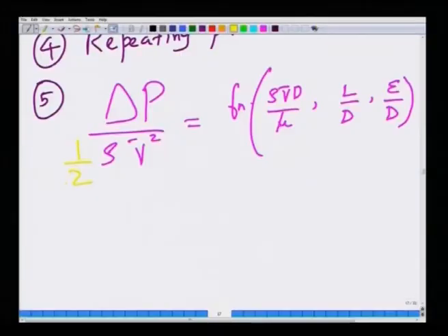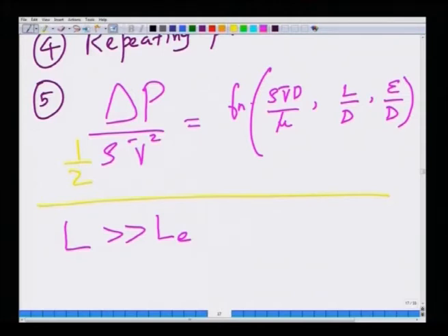We cannot say that from the non-dimensional analysis, it is just a matter of practice. Now, this is valid always, it is not a function of whether the flow is laminar or turbulent. We have not assumed anything like fully developed flow, we have merely done dimensional analysis on the pipe flow problem. Now, suppose we want to specialize this. Let us say the length of the pipe is very large compared to the entry length, say the entry length is just 1/100th of the length of the pipe. So, in a predominantly large region of the pipe, the flow is fully developed. Therefore, in such cases we can neglect the entry length and focus only on the fully developed flow region.